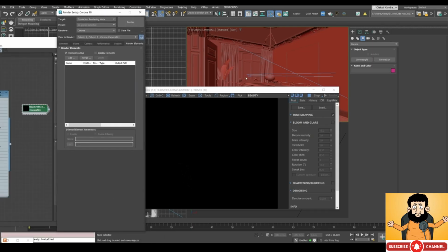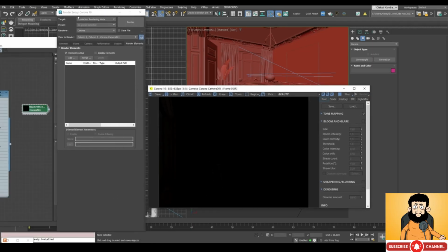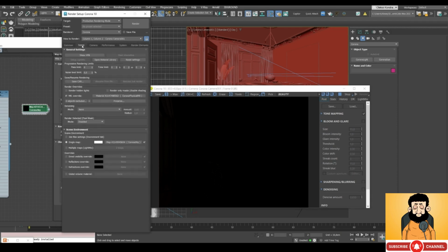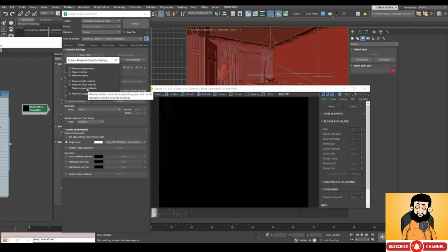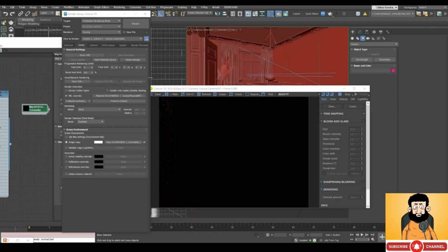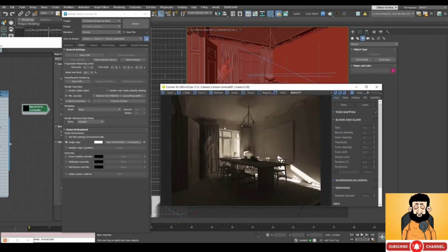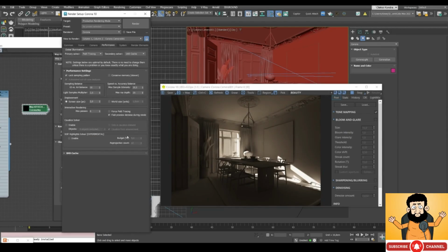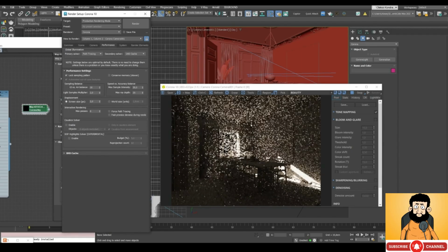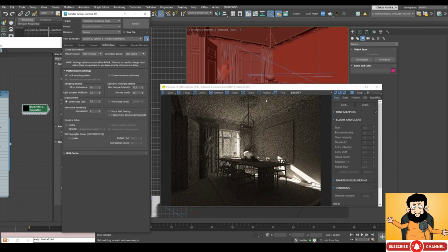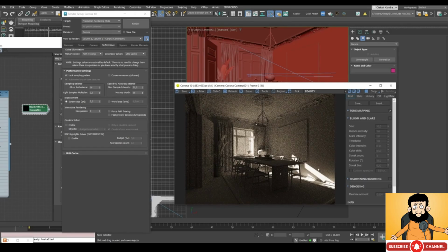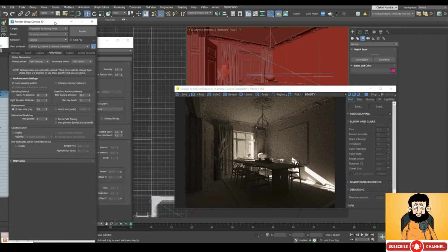Okay, let's move on. We have some windows on the scene with material setup. So now I'm gonna click Scene tab, click Preserve button, and simply check the Preserve Glass Material checkbox. So as you can see, the light is now coming through the glass. That's good. Next we go to Performance section, uncheck Fast Preview Denoise so that we don't have this blurring effect. And now the sunlight is right inside the interior.